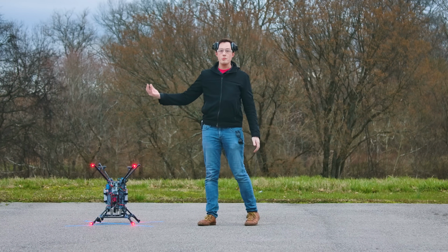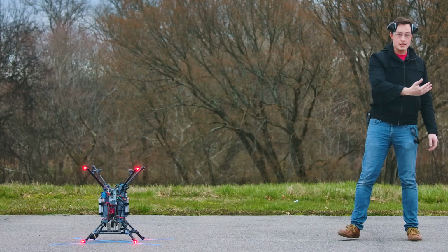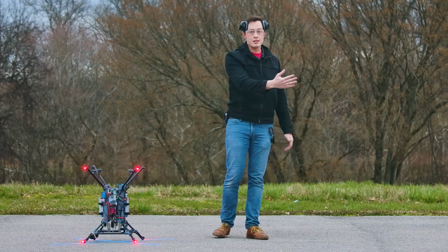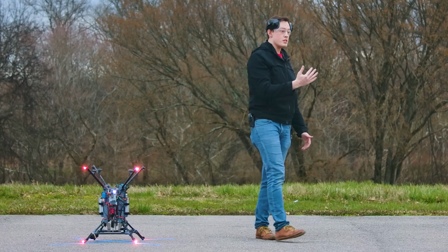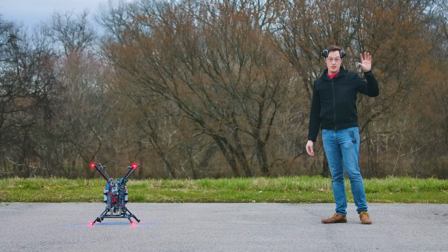We're gonna go up 1 meter, hover for 10 seconds. We're gonna go over positive on the y-axis. This is local to the craft. We're going over 2 meters, positive on the y-axis. That's gonna take place over the course of 4 seconds. We're gonna hover here at that 2 meter deviation on the y-axis for 10 seconds.